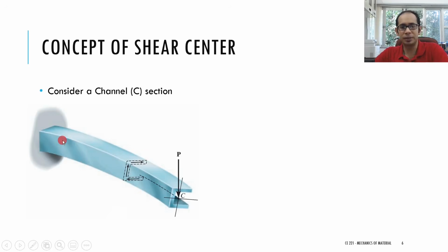This is again a similar kind of beam which I have taken, where the load is applied through the centroid. Now if you take an internal section over here, this is the resisting force that you are having. This resisting force equals P, and then because of the shear flow, remember we have considered the shear flow over here, you are going to have these horizontal loads acting on the top flange and the bottom flange. Remember, here again the top is the flange, the bottom is the flange, and the middle portion is the web. Now I hope you are clear with this direction of the forces.